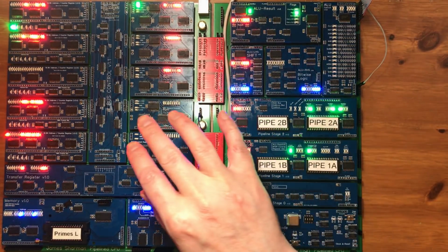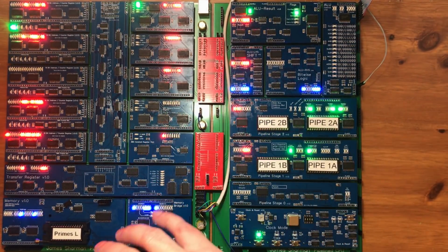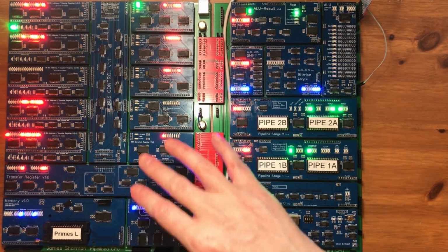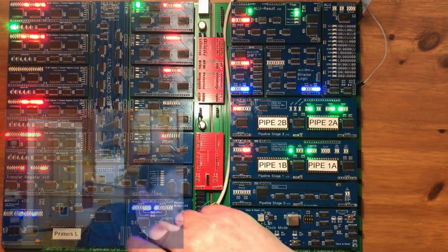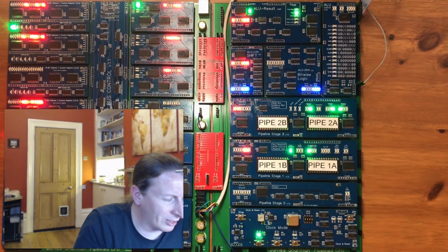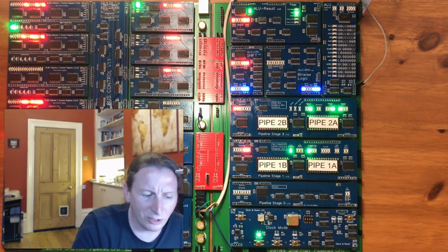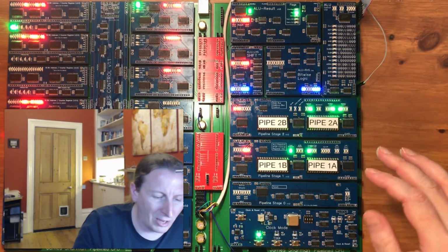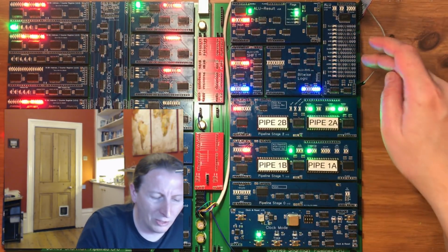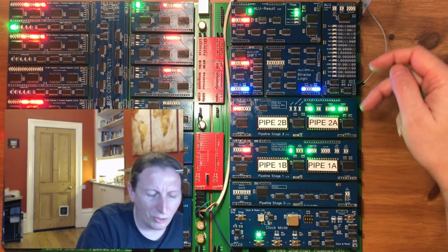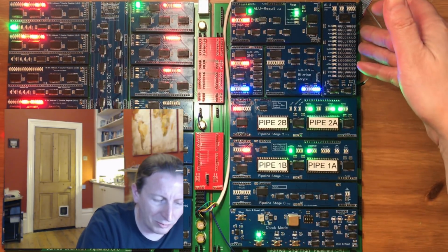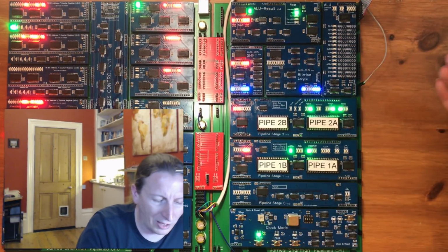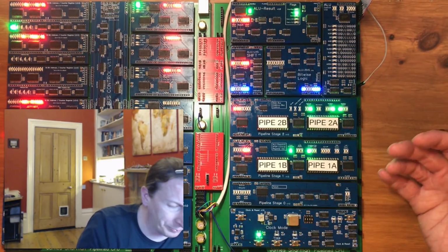Now you've got 3 to 8 line decoders, but you've also got 4 to 16 line decoders if you search around in the 74 series chip lists. I also show how you can combine these in different ways to get whatever decoder set you want. The second path I have is in the ALU, where I turn 4 control lines into 8 control lines by using this diode matrix. Or you could use a second tier of ROM there in the same way I described earlier.